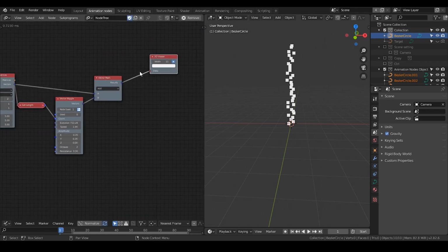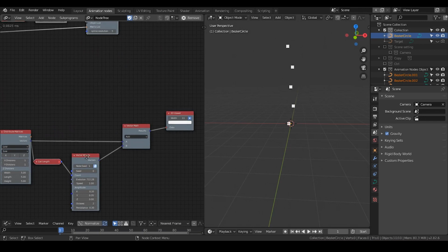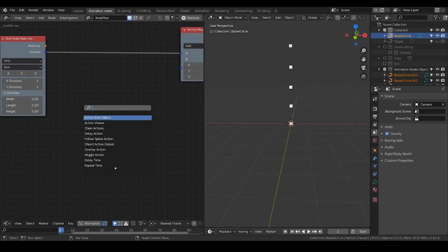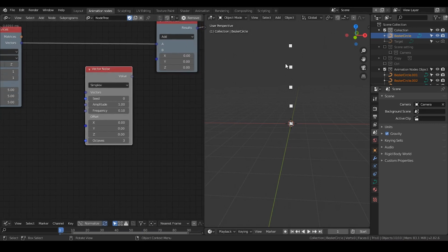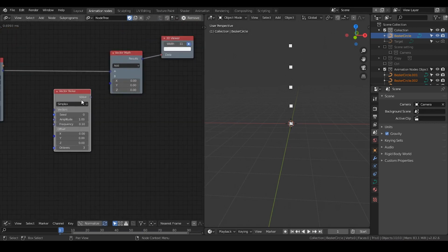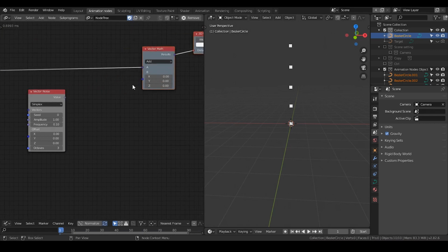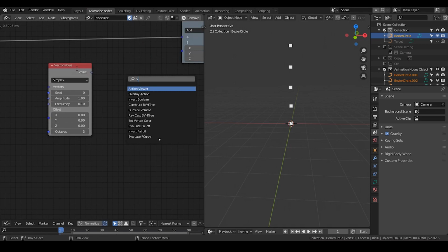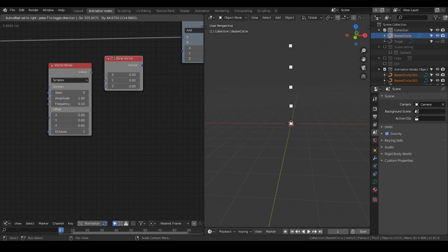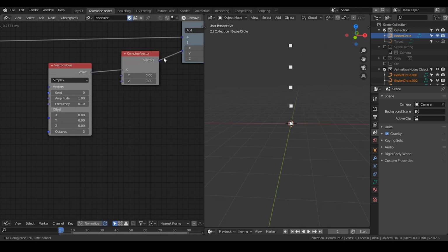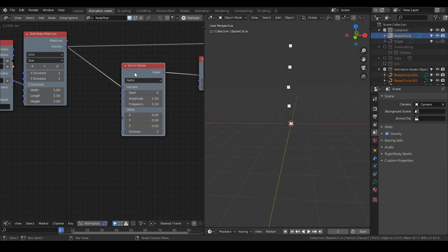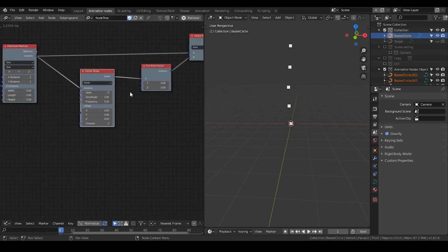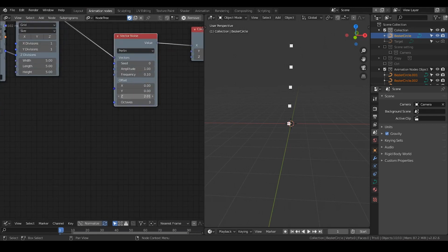So here we're going to do a kind of different method. So let's take the spline back. I'm going to use a different method. It's called a vector noise method. So currently vector noise is a 2D noise, which means it will generate a line. So you can see it outputs a float value, but we need a vector. So let's just make a combine vector and plug that to X currently. I'm going to change the type into Perlin because I think Perlin is softer. And then I'm going to put this vector into vector so that it generates kind of 2D lines. And by animating these offsets, then we're wiggling these splines coordinatedly.